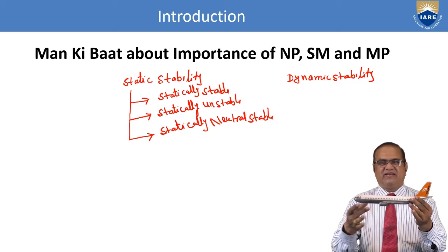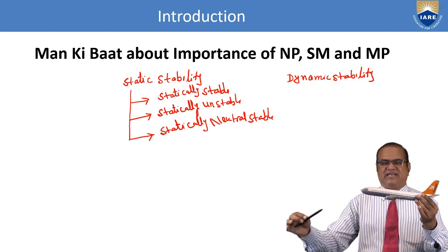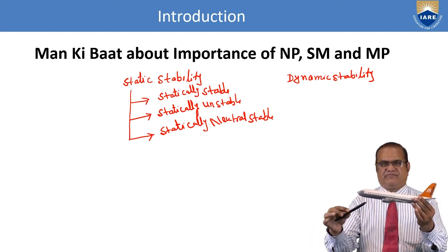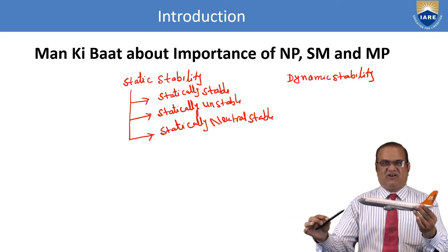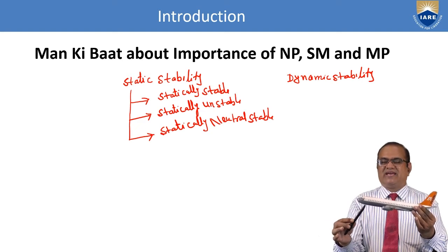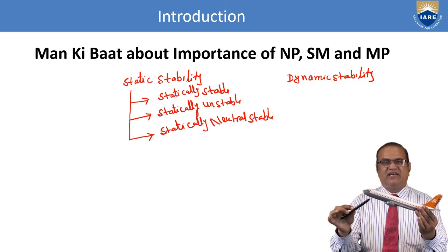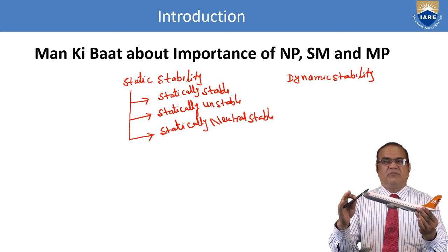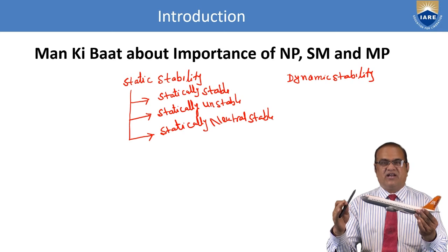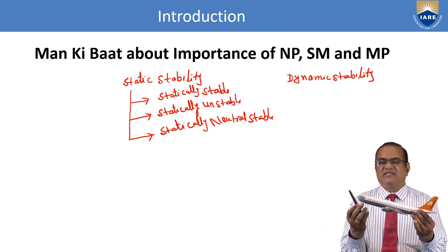As and when a gust comes from any direction, I am assuming it is from the bottom, the aircraft experiences this additional gust of wind, which will try to make the nose go up. This additional force will disturb the aircraft attitude. Previously it was in steady state flight; now it will change its orientation, and if it is a bottom wind, the nose will be up.